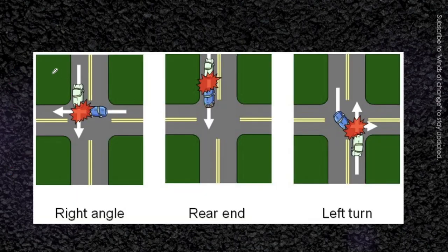Let's find out how. These are the right angle collisions that can occur, which we have already discussed. These are being reduced in case of the provision of signals. In case of rear end collision, that is when there is a change of the light, there can be a possibility that this vehicle stops and this vehicle may hit it if it is not capable of stopping in the time provided by this vehicle. There could also be a possibility of left turn provision, which is also being avoided in case of the signalized intersection.